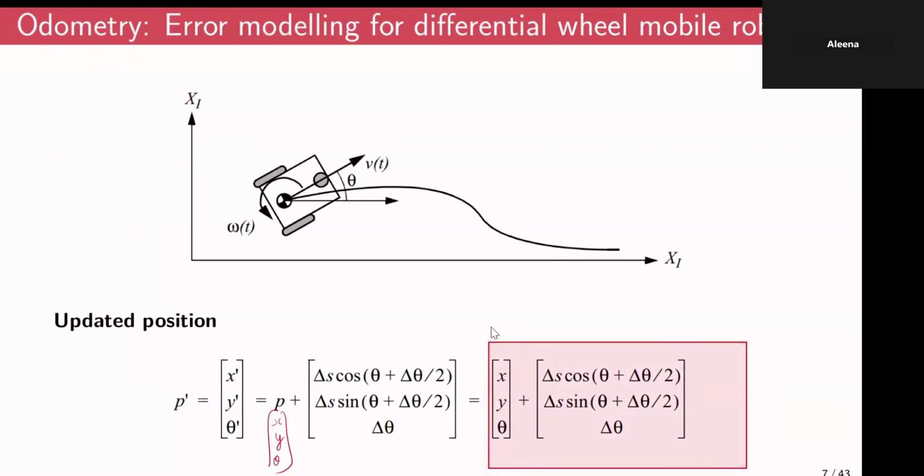Right? So that is about odometry, estimating the new position or the new location of the robot just by using the information from the inputs or information from the encoders. So notice that at this point, we are not using any information from the sensors. We are purely relying on encoders, purely relying on the wheel motions.